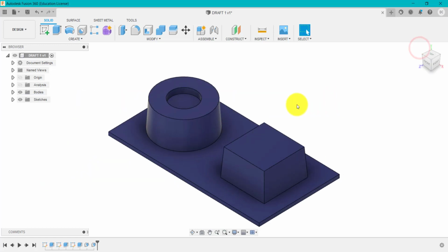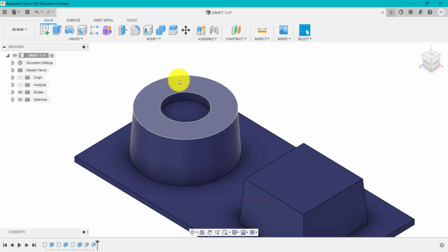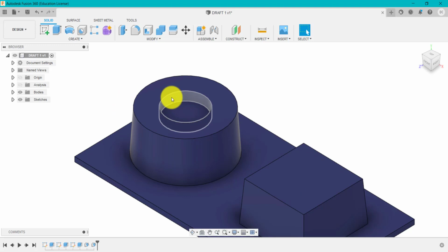And then we come to the home. You can also use it on internal faces as well. So if this is a vacuum former or mold, and we wanted the plastic to come over this and be easy to remove, we'd also want to add one on here as well.